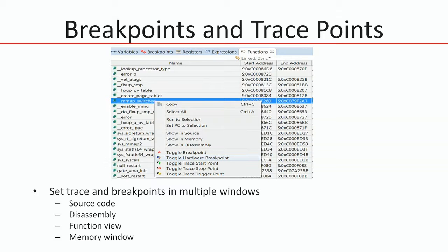A lot of the art of using a real-time trace is filtering down to get the information you want rather than capturing vast amounts of data, which just means you're looking for a needle in a haystack. So trace filtering and trace regions are extremely important when you start to work with real-time streaming traces.